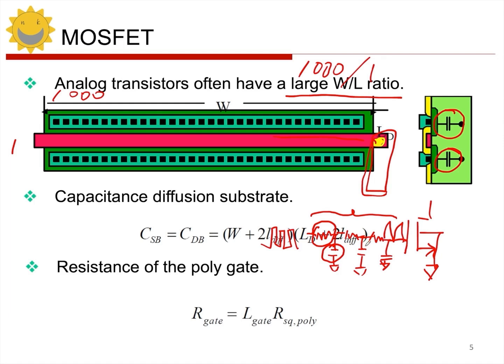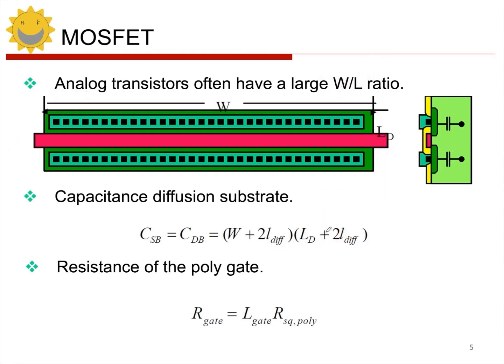It's gone. So compared to the source drain issues we mentioned earlier, this is even more serious, because the source drain issue just means that my parasitics have increased, right? But the parasitics of the gate could potentially lead to the transmission of the signal not keeping up, and it just disappears, right? It just vanishes.